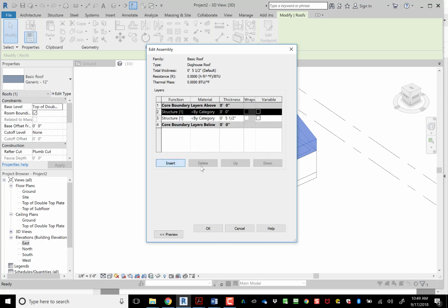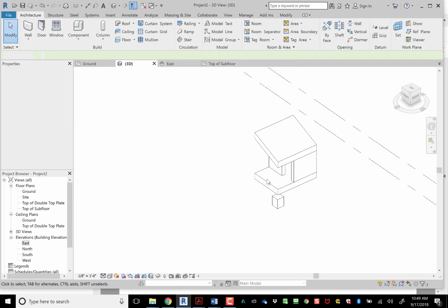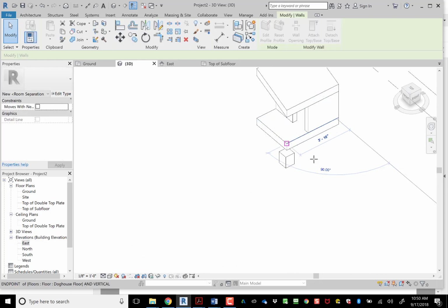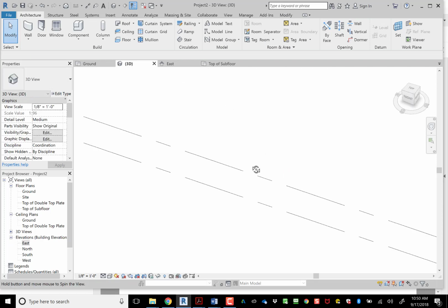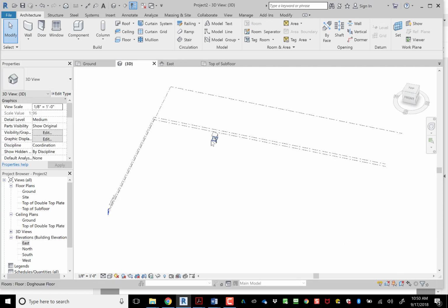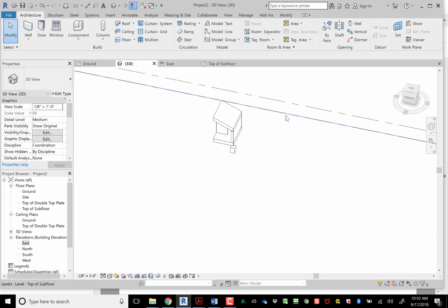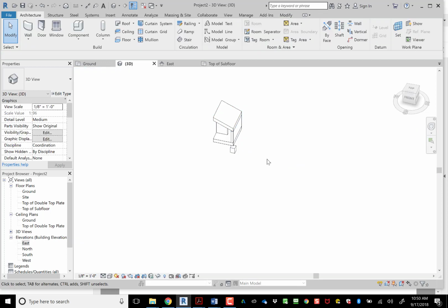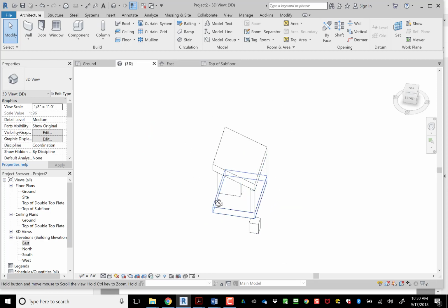And then I'm going to add, again, I have to check those tables, but I'm going to skip it for now. I'm going to just do 1/2 inch sheathing. Might be thicker. And then here's something that I need to show you guys. So this wall, again, I'm just copying the student's design. I'm pulling it out. If these level lines are distracting me, I'm just going to click on them, hide in view category. And then when I zoom in and orbit, oh, it's still not orbiting really well. There must be something somewhere that's causing it to orbit weird.